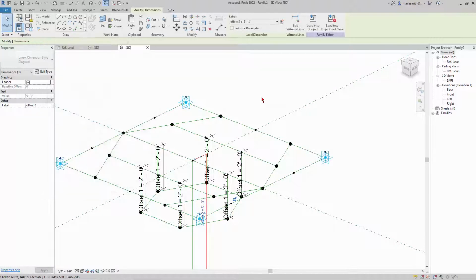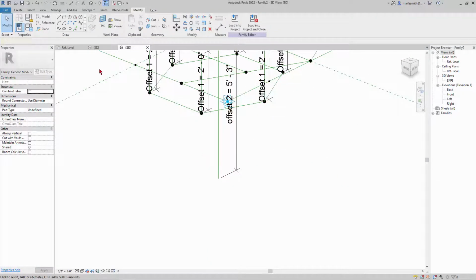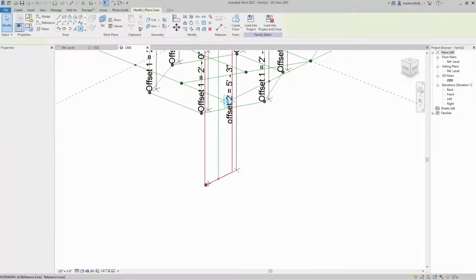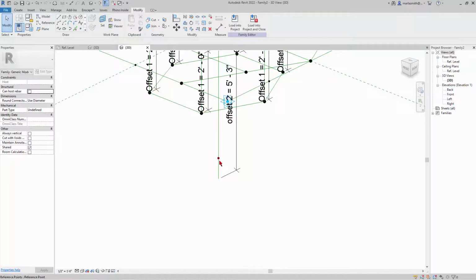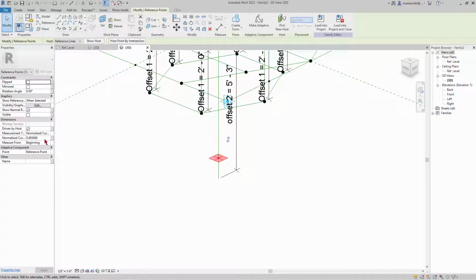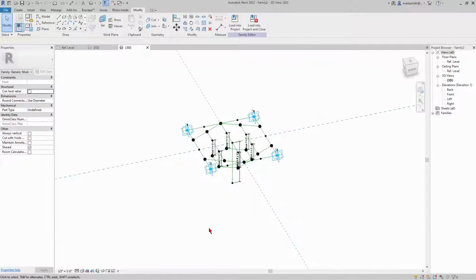Okay. And you know, we're going to have a whole bunch of little points coming down here, so I'm just going to place a point there so I can see it a little better. And again, when you place a point, you want it to host on something. You want it to be not on work plane, but on draw on face. And so when you do that, you'll see it'll get small and host itself to that, and I can pick it and just set it to 1. So that guy's down there. All right, so when I come back, we'll put the triangles on it.